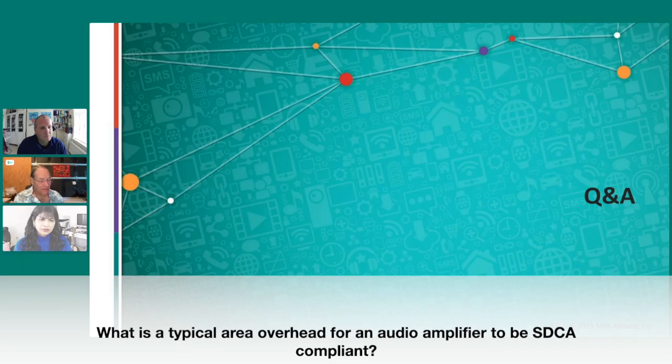So between the manufacturer ID, which is 2 bytes, the device ID, which is 2 bytes, and then one more byte required for version information, you're required to essentially have 5 bytes of ROM in your device. That might very well just be fixed with gates, or you might have some pins to strap things, or you might have a couple fuses if you have a single die that you're using to make multiple products with various features. But I think I gave you the example: the overhead's quite low, on the order of 5 bytes of ROM.